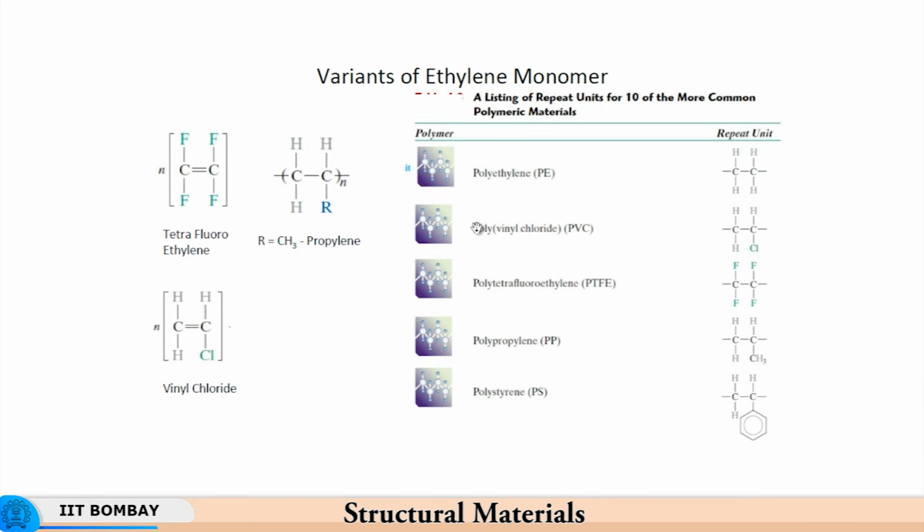In fact, in most of the batteries in electric vehicles, you have the polypropylene being used as a material for the separator, and that is because it has got a metastable phase which changes during deformation and generates the kind of porous membrane which is needed for a separator in the batteries.